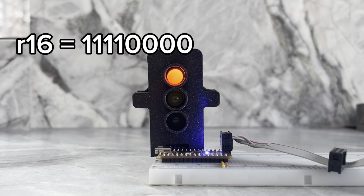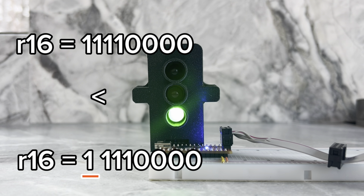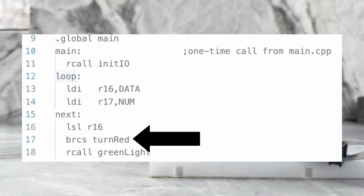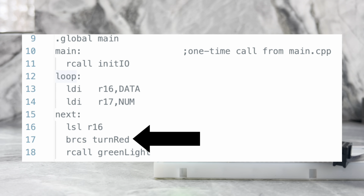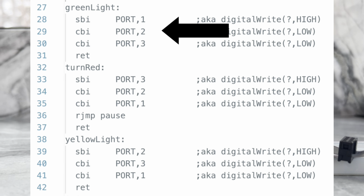Since the value within register 16 is bit shifted right, every time the overflow of what is within the register is equal to 1, something called a C flag is turned on. The branching statement checks the C flag, and if there is a 1 inside of it, it will jump to the turn on the red LED command. If not, it will turn on the green LED.